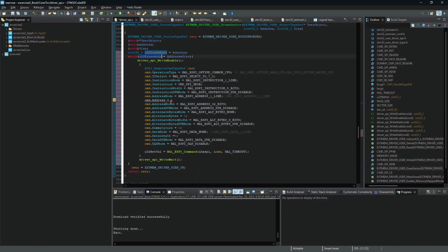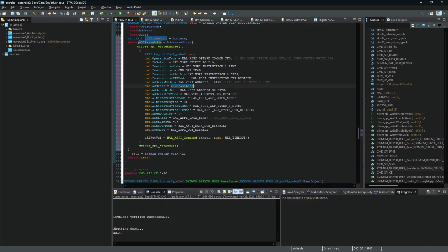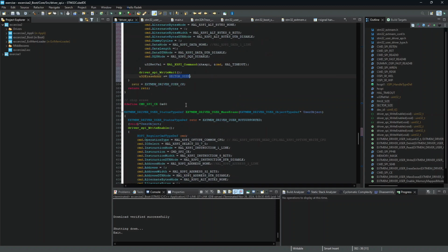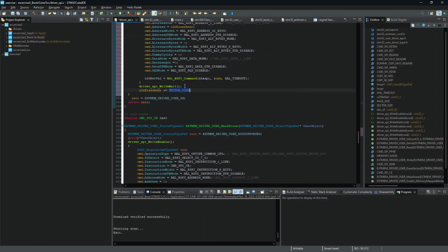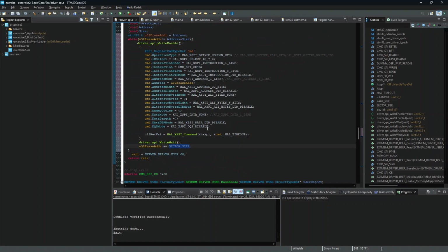And okay, we erase this address. After the erasing, I think the last part what we need to do is to increment again the erase address with the sector size, which I believe I defined too. We can check that, yeah, sector size is defined too. And this should do for us the erasing of the sectors.